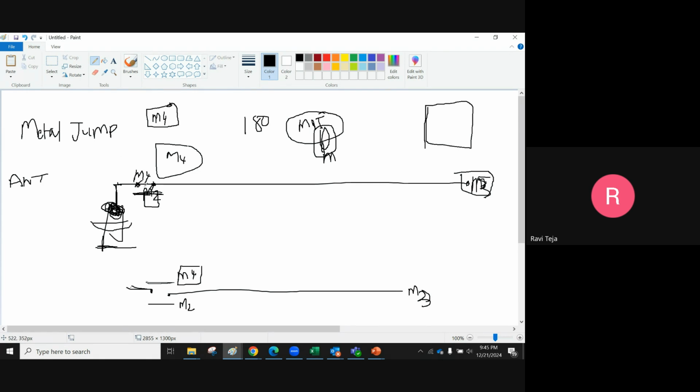Why I will chop is I want to create some open circuit and then remove this charge before reaching this gate. Then if I build some other metal after the next metal, this charge will be gone. There won't be any charge left over. Now my question is, when you have antenna on M3, you can go to M2 also, but you are going for M4. I am asking the reason why we are going for M4 instead of M2.